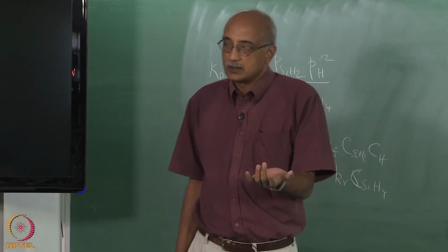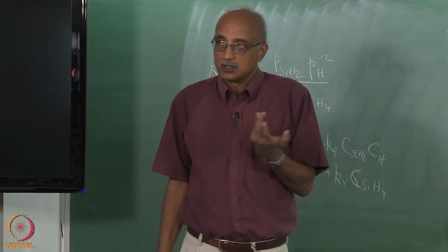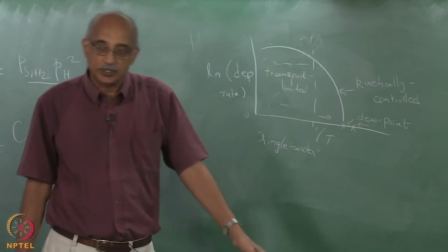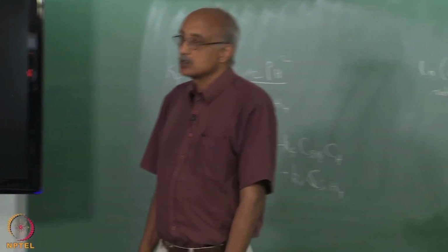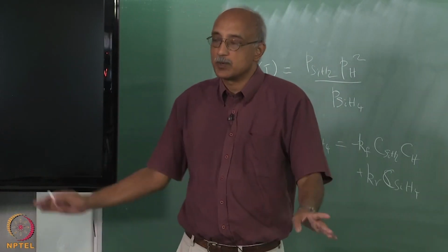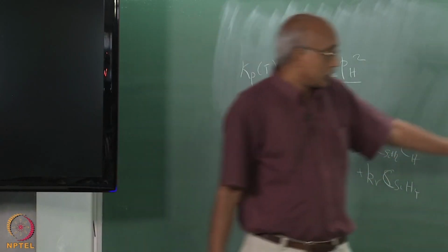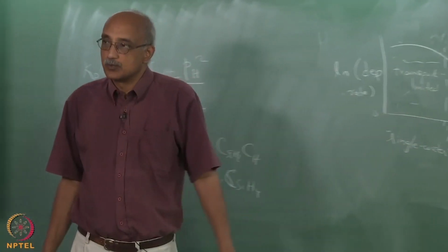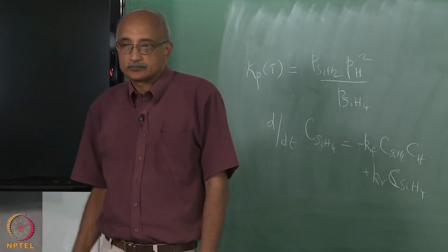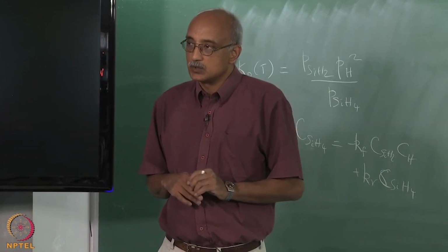On the other hand, in this regime, your flow controls do not have to be very tight, except as far as they affect the temperature distribution. But what you need to control very, very carefully here is your temperature distribution. You have to make sure that the temperature profiles are maintained absolutely constant. You have to have the best possible control mechanisms for temperature, just as you want to have the best possible control mechanisms for flow in this condition, right. So, from a process control strategy viewpoint, where you focus is very, very different in these two cases.